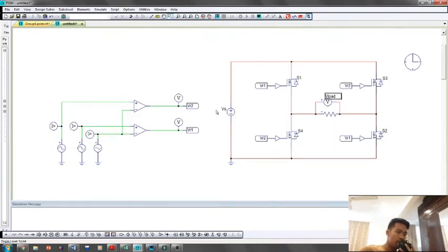This is achieved by pulse width modulation of the inverter switches, and hence such inverters are called pulse width modulated inverters. The power switches are controlled based on the comparison of a control signal and the triangular carrier wave, which is made in a comparator. When the sinusoidal wave has magnitude higher than the triangular wave, the comparator output is high, otherwise